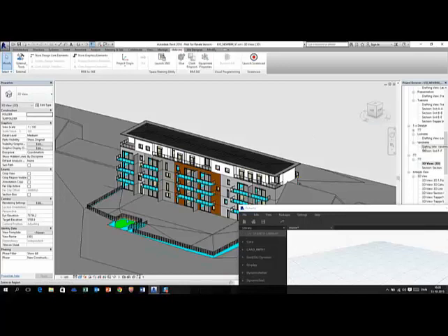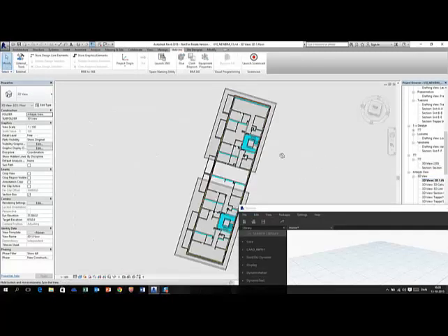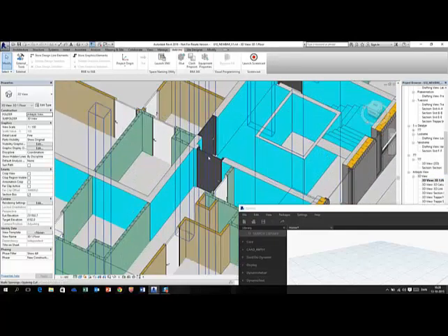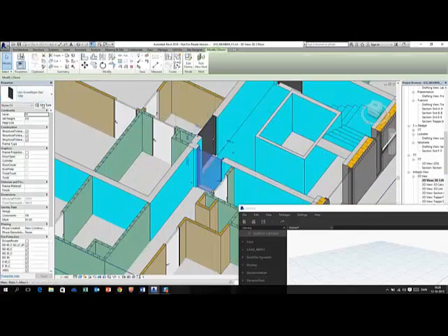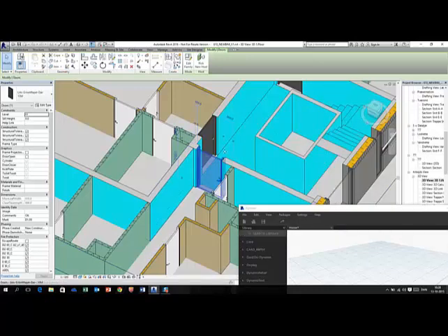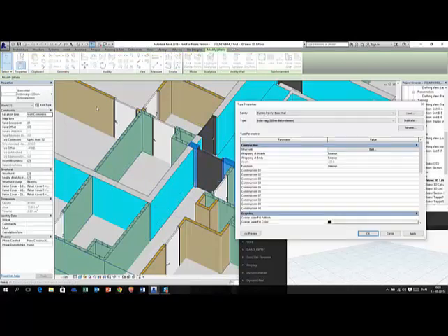The example I'd like to show you here is an issue that I've seen in database work with Revit. When I look at the door here, you would see that it's an exterior door as a function, since it's been located between the hallway and the staircase. And if I look at the wall itself, it seems that it's an interior wall, which I would consider a mistake.